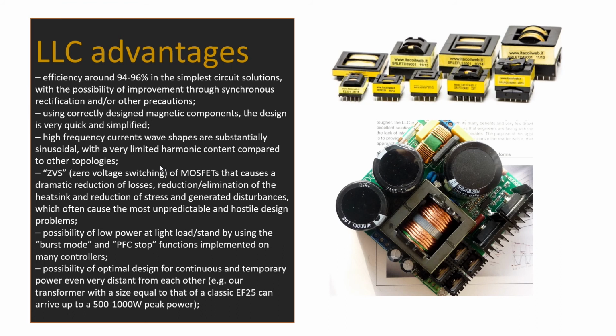As a lowlight, they cannot work with a broad input voltage range. You need either manual or automatic switching between 110 volts mains and 220 volts mains. And designers need excessive magnetics knowledge to properly design such power supplies.